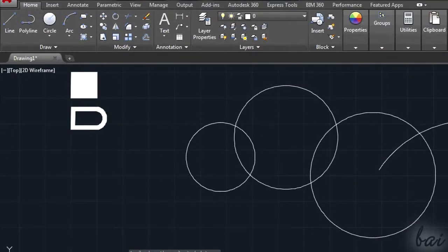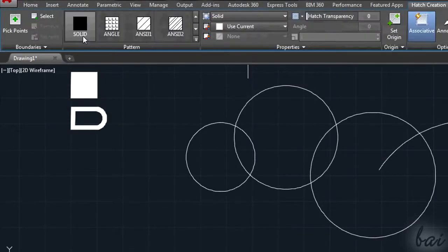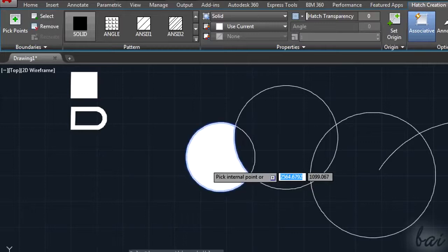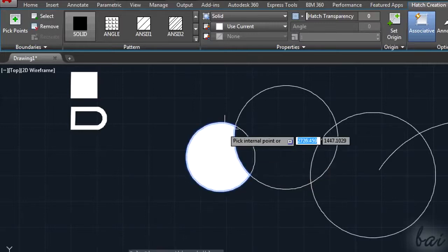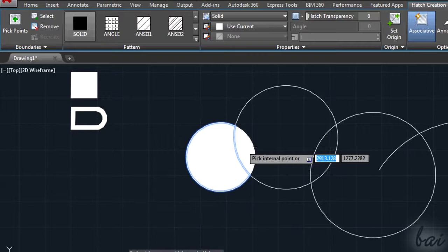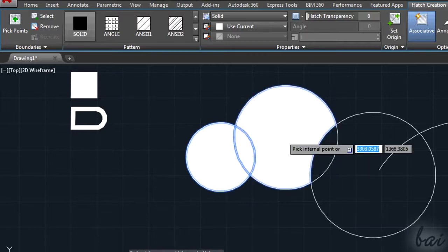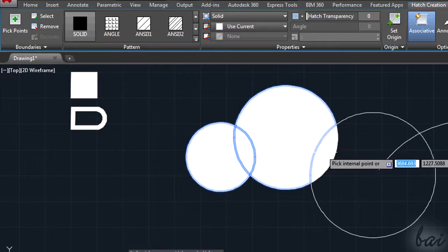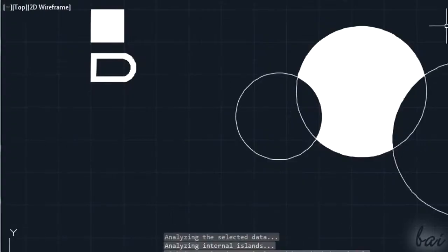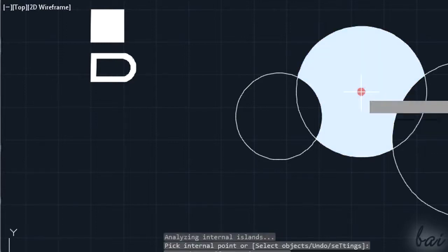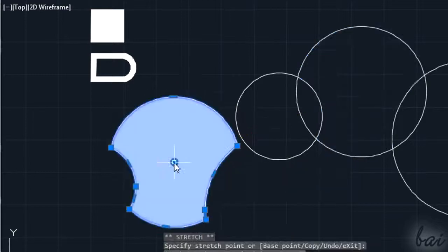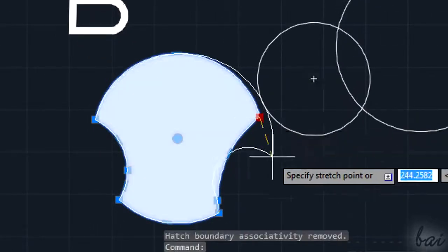The Edge tool adds patterns inside any closed boundary, composed by any kind of objects. What counts mostly is the first boundary met. So if you need to cover what is over a certain boundary, you have to click on and on where needed. These patterns are objects themselves, indeed, that you can move through their central point and edit freely using the other blue nodes.